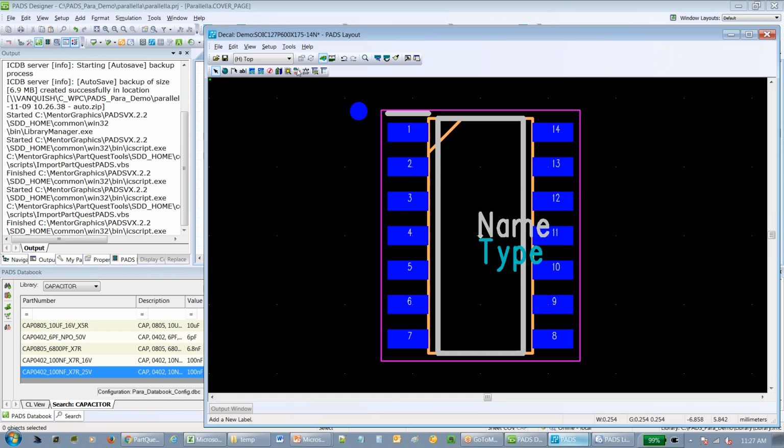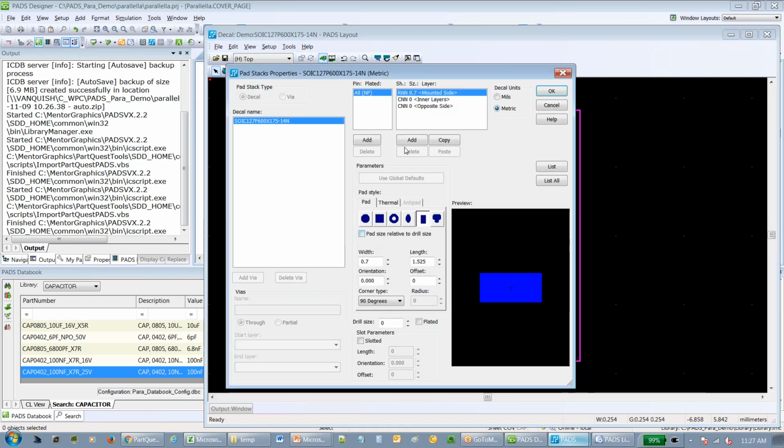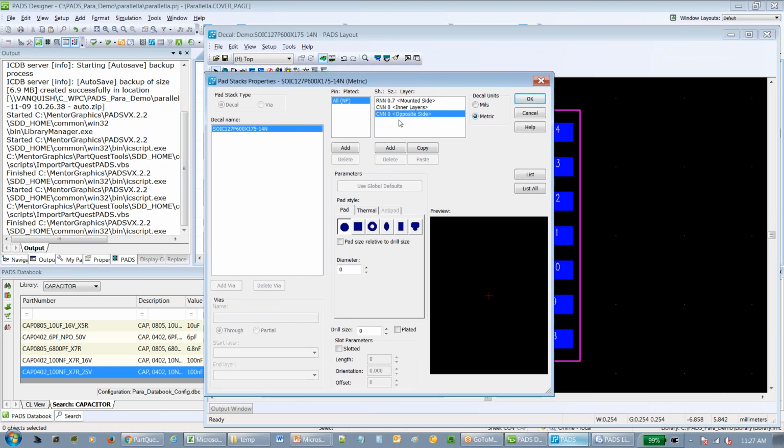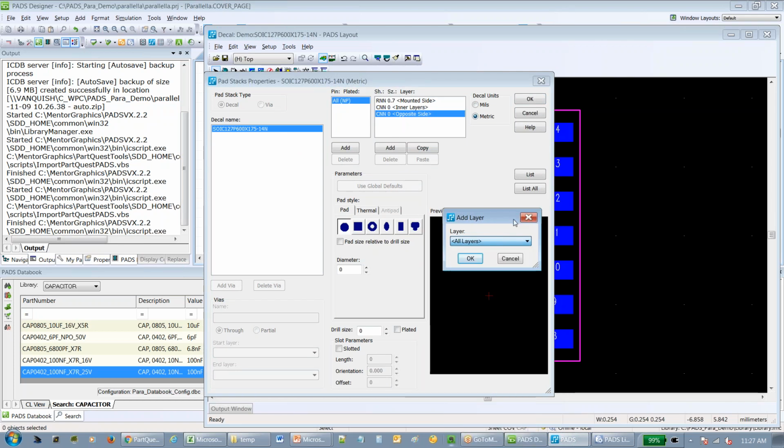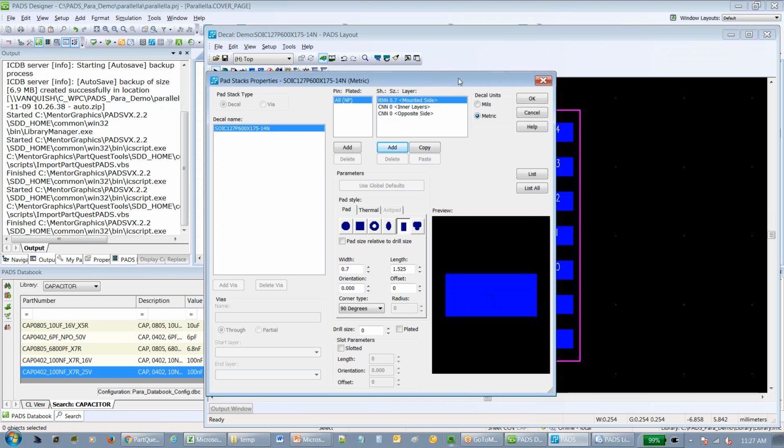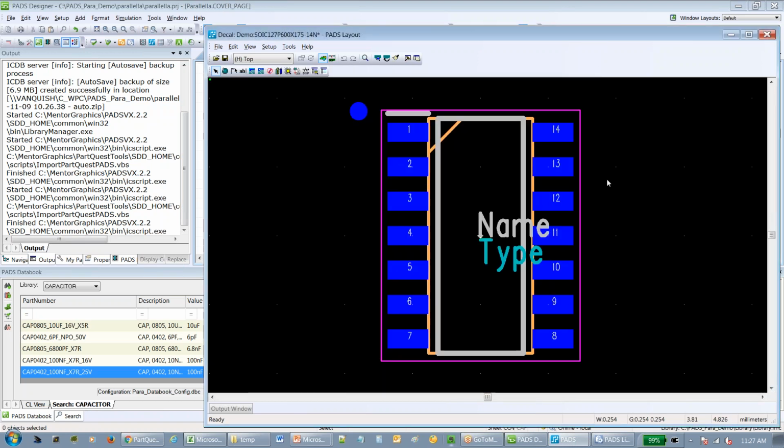Another thing to really think about when making parts is to add extra pad stack information on your device. Okay, so a lot of the library content that is downloaded will automatically have the solder mask and silkscreen pads added, but I like to put stuff on the assembly layer as well. So when I create my assembly drawings, I can turn pads on if I want, and it makes my assembly drawings look a lot nicer for visual aesthetics. So something else to think about adding.